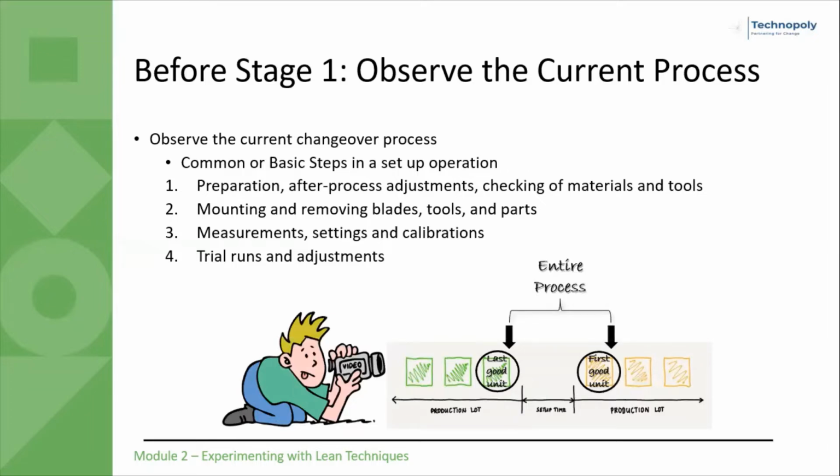After which, we may show the video to the setup person and other people involved in the setup. Ask the setup person to describe what he or she is shown doing. Have the group share their thoughts about the operations. Study the video in detail, noting the time and motions involved in each step of the setup. Also, you can use a stopwatch if necessary.